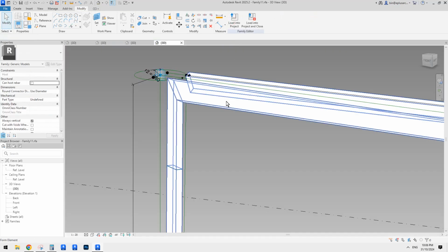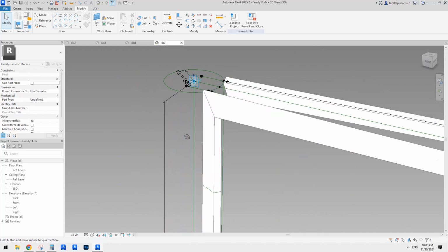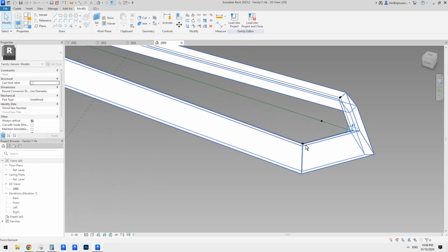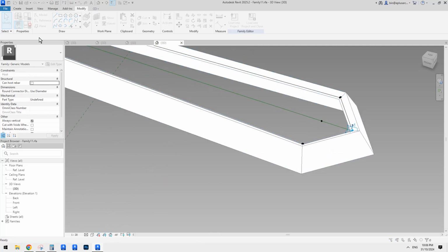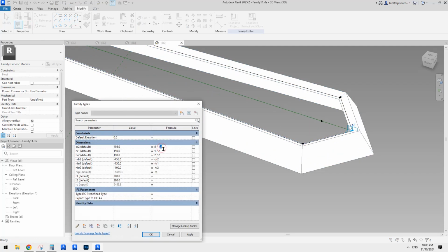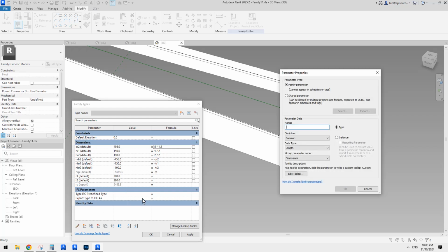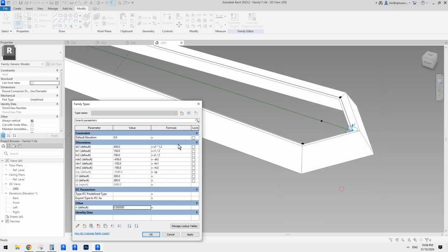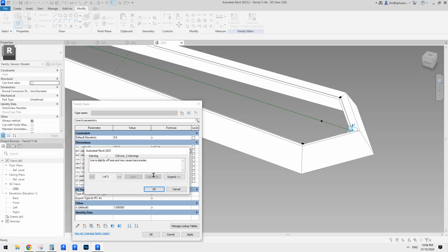I didn't have that parameter in that. I used 1.2. So maybe we can just create a parameter. So for example, I'll create a parameter called n instance and use a number, and then I'll just put in 1 for now, and type times n instead of 1.2. So click OK. That's all good.